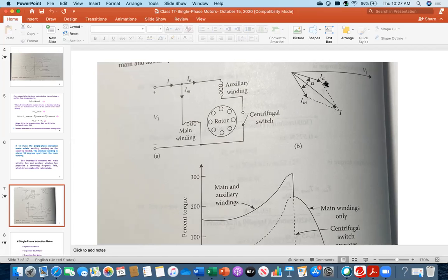That is the reason. Now everybody see, this is showing the power factor angle between voltage and current. Because this is IA, it has higher resistance than this one. If it has higher resistance than this one, this means that this one is more lagging. As I said, if resistance is zero, for example here, then this will be fully 90-degree lagging. Similarly, if its resistance is zero, it will be fully 90-degree. I mean, both will superimpose. Both will be on the same line.